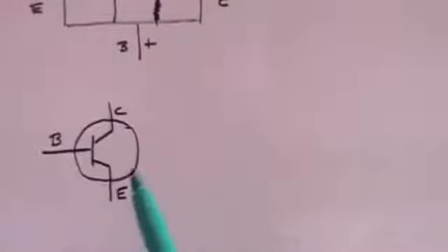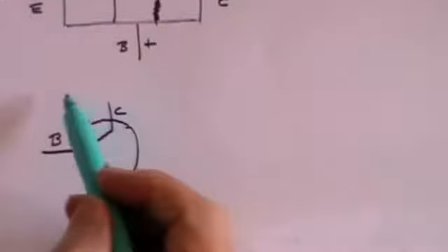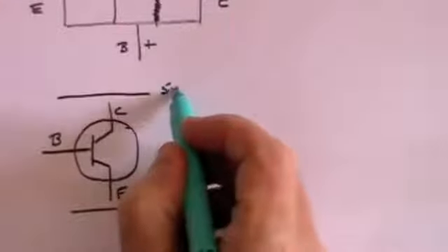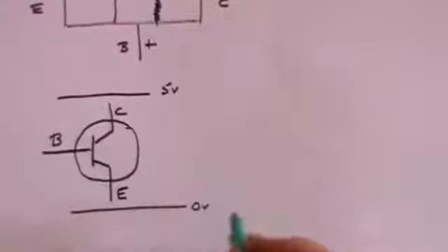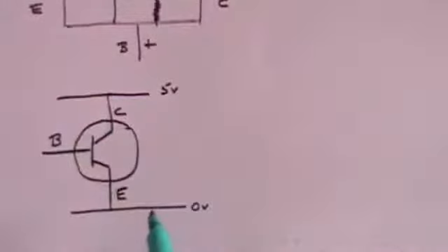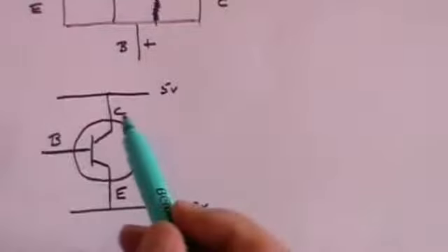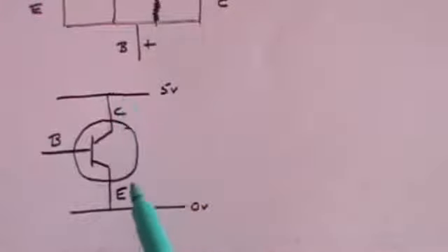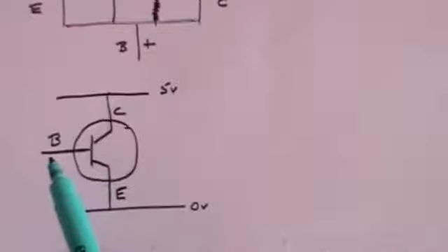And the same principle applies: it varies for different transistors, but let's say you have 5 volts here and 0 volts here, and we better join up the wires so that there is a link. The electrons are going in this direction from the emitter to the collector, so the conventional current is coming in this direction down the voltage. So no current will flow through that transistor if there is no voltage on the base. But if you put a voltage on the base, then a current will flow through the transistor.